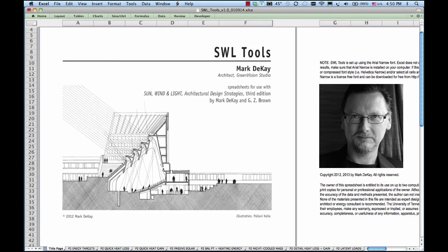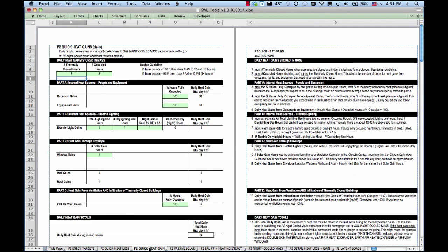Welcome back. This video takes you through the quick heat gain process for calculating daily heat gains that will be used to calculate the night-cooled mass system. So I'm going to go right over to the P2 Quick Heat Gain tab, and here we are looking at the worksheet for quick heat gains on a daily basis. So we'll use this quick method to estimate the daily heat gain that has to be stored in a night-cooled mass system.